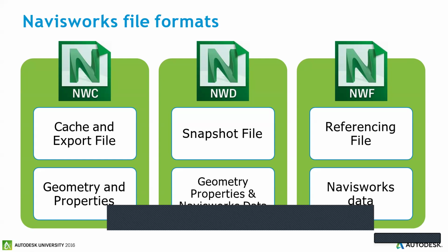And then you have the third format, which is known as .nwd. This is the part where all the coordinated models together are shared with the vendors or the project manager, right? Who will be managing your project? All these three files for the other domains get integrated into .nwd format, and then they're shared with the other vendors. So this is the difference between all these three files.